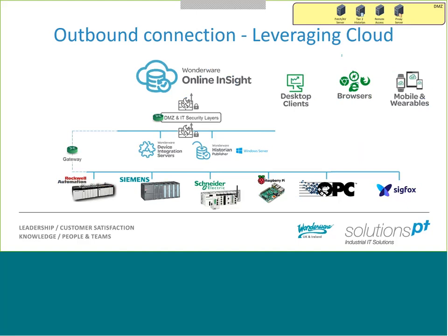The advancements of cloud, or things that we realized very quickly, is that you can see lots of different variants of IoT solutions. What we're not necessarily talking about here is linking complete SCADA and MES solutions through the DMZ to the cloud, but linking things like PLCs directly or devices, web services, but they still have to go through that DMZ to that cloud environment. So we're not utilizing local controls, etc. We see this through a good number of customers where data analysis is paramount, but security measures should still be taken to secure the connections through that DMZ.